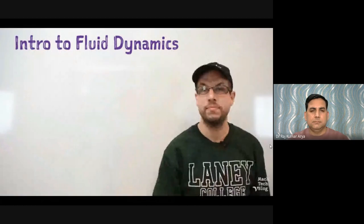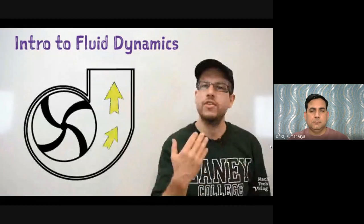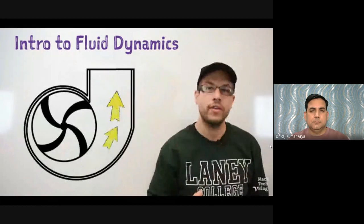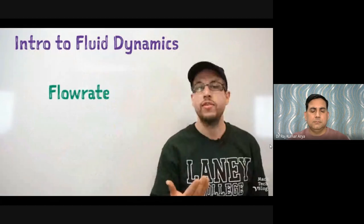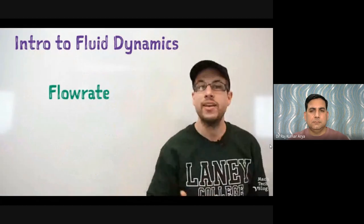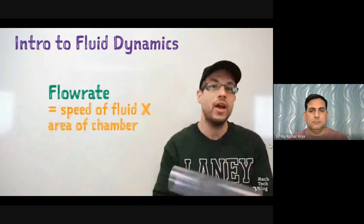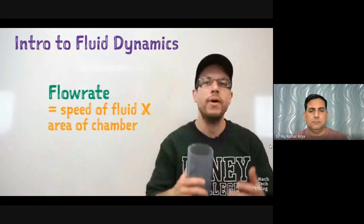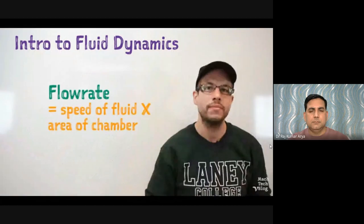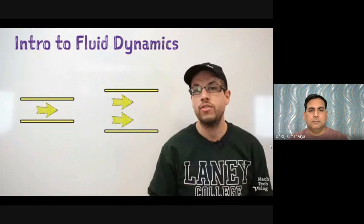As fluid travels through the volute chamber, it actually starts to slow down as the area of the volute chamber increases. That's because flow rate, or the amount of fluid which is moved during a given length of time, is dependent on two factors. One is the speed of the fluid, and the other is the size of the chamber through which it's moving, meaning how much of the fluid is moving at that speed. If the flow rate is constant, then an increase in the size of the chamber would result in a corresponding decrease in the speed of the fluid.